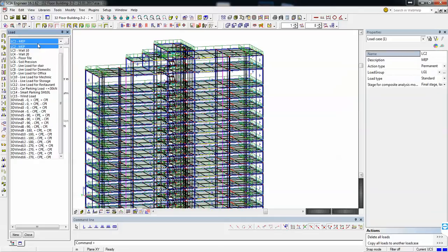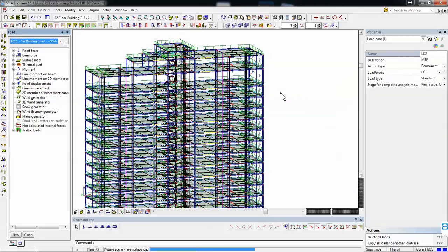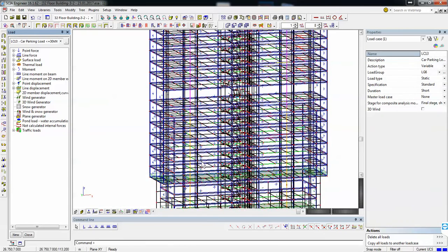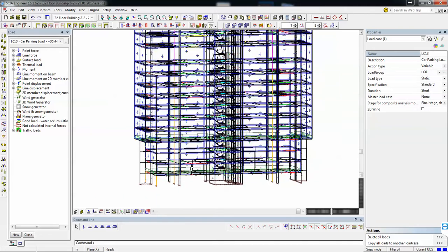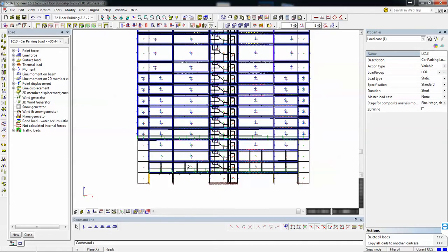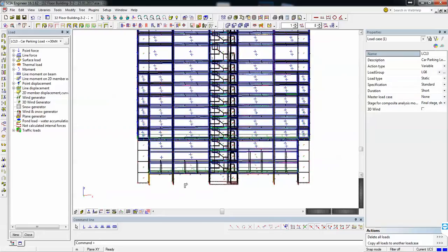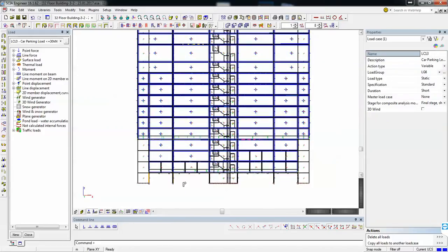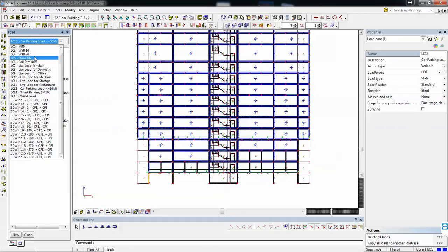You didn't place the smart parking load, or you did it as a uniform load? My suggestion was to place the load as point loads, because you had that system with legs, so you need to see the reaction of each leg and place them as concentrated forces, not uniformly distributed forces, because it will influence the design and the behavior of the elements where we place them.